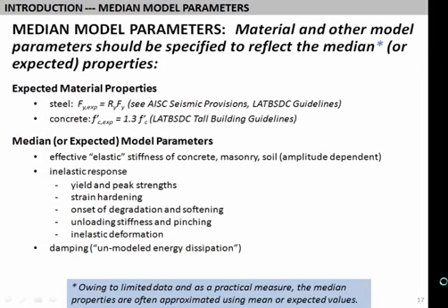When you look at deformation capacities, when you're putting in hinge rotation backbone curves, these things should all be like the average value, if you will. So we want to be starting our analysis from capturing the average behavior and then think of things from there. This is contrary to what you might do in certain practice, where our tendency as structural engineers is to, quote, be conservative, given a lower bound on the stiffness. But when you're combining shear walls and frames and other elements, what's conservative is really unclear.